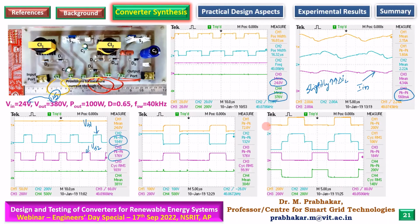So we arranged the devices, we interleaved, and then we arranged the components. We got the voltage lift technique. There the voltage gain was 4, doubled. And then we had a coupled inductor, we had a voltage multiplier cell. Based on the coupled inductor turns ratio, which we haven't explored so far, we are expecting more voltage gain. This is the sequence in which we are fabricating the converter.